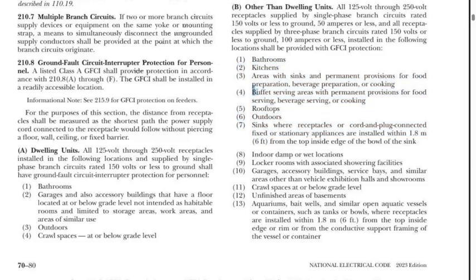All right, where you can have a buffet area, obviously restaurants and things like that. Aquariums or something like that, hotels or bait wells and tackle shops. You have locker rooms, all these different style of places where GFCIs have to be used.